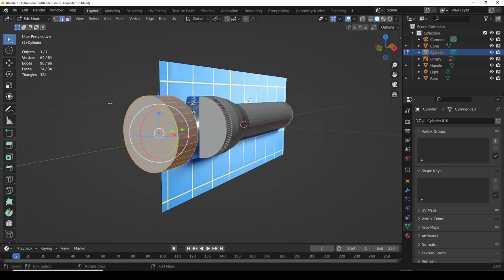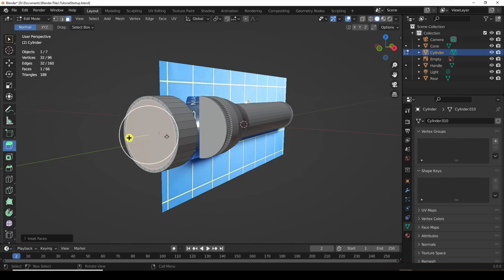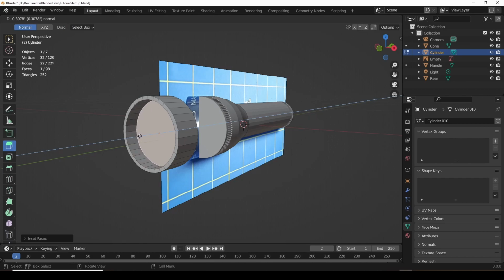We're going to select this, go into edit mode, and go into face select mode, and I'm going to click on this to select this front face, and we're going to use our friend, the Inset Faces. Click on that, and it gives you this little circle, and click on the circle and drag inwards, and it will give us a new face. And then we can use our extrude to bring it in. So we extrude it in, and now we basically have our front object. All we have to do is bevel it.